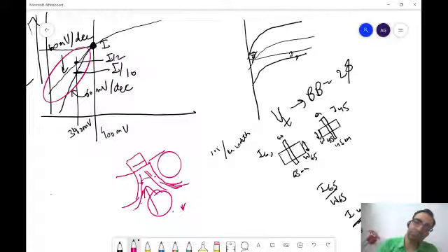Inversion is when there is a WD max, which we discussed in the office hours also, and then the inversion layer forms. Now, what we have said is that we are lower than VT, but there is a depletion region. So some charge will enter the depletion region, and through the depletion region itself go into the drain.